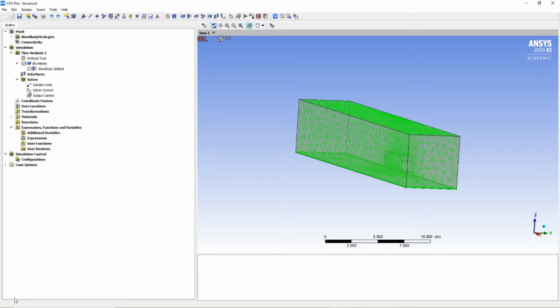Now, this time around, we're going to create what we call composite regions. An imported mesh may contain many 2D regions, but for the purpose of creating boundary conditions, it can sometimes be useful to group several 2D regions together and apply a single boundary to the composite 2D region. In this case, we're going to create a union between two regions, which both require free slip boundary.